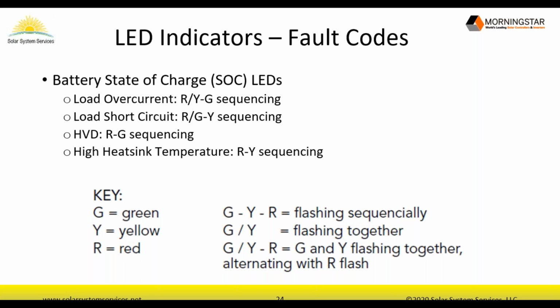I've seen the same thing happen with some LED power supplies that may have a high surge startup to it. So anything, or a motor or anything with a high surge or high startup to it, should not be connected to the ProStar directly. And if you made that mistake, you'll probably see that flashing sequencing there. That's going to probably tell you that's what that error is.